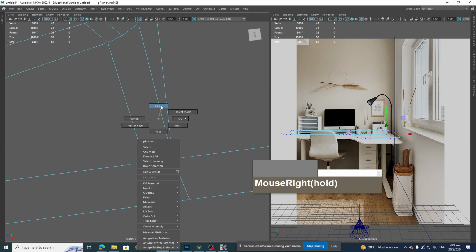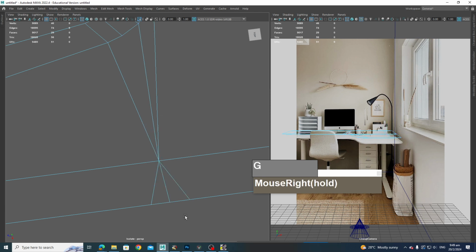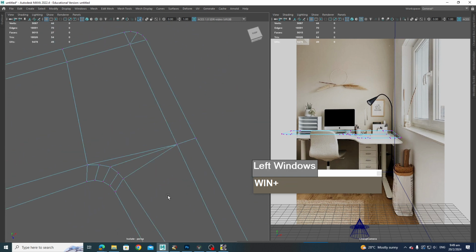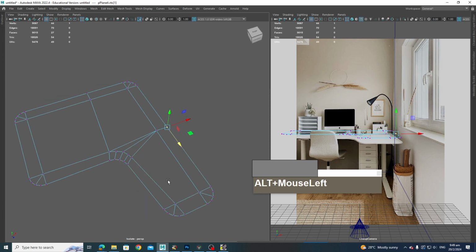Then same for this one. Collapse the edge by repeating the command. Same for these edges over here. Press G to repeat last command for the edge. Okay, so essentially I fixed this area. Now these are four-sided edges. Although I will probably now slide this up.